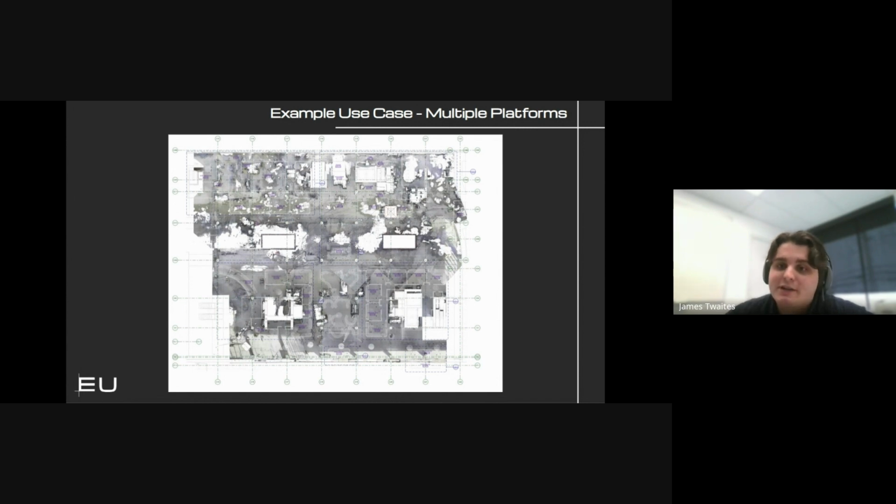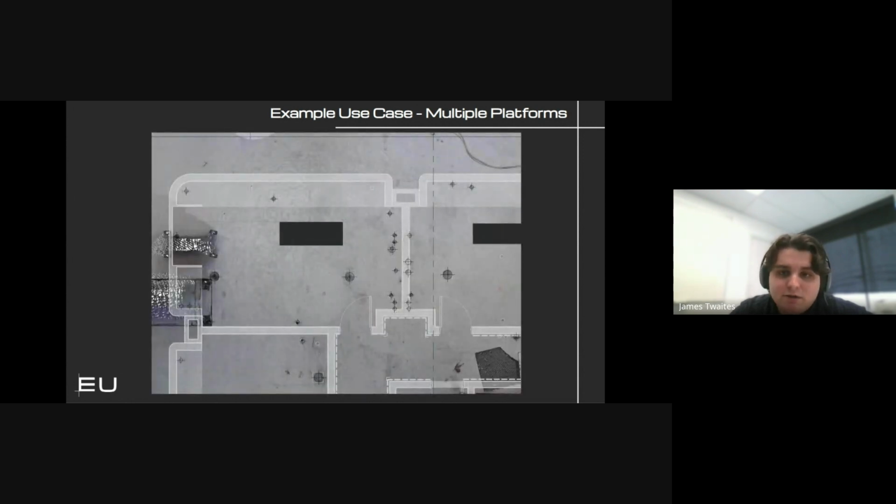It's important to understand the limits of your technology. So we isolated only the points near the top of the slab, and I created new elements to add to the federated model so that everyone gets a better understanding of where the cans and the drains are that are already cast into the slab. And I've shown those locations with crosshairs here so that we can check the alignment with the equipment going in above.